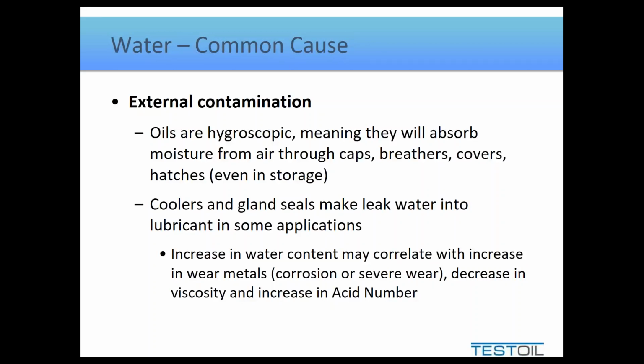The water may be pressurized in some systems, so that generally speaking, the water always migrates to the oil rather than the oil migrating to the water. But some systems are more balanced and you'll get a little bit of both happening. So it's always important to understand what possible sources you have for water and what follow-up actions you can do to confirm if one's more logical than another.